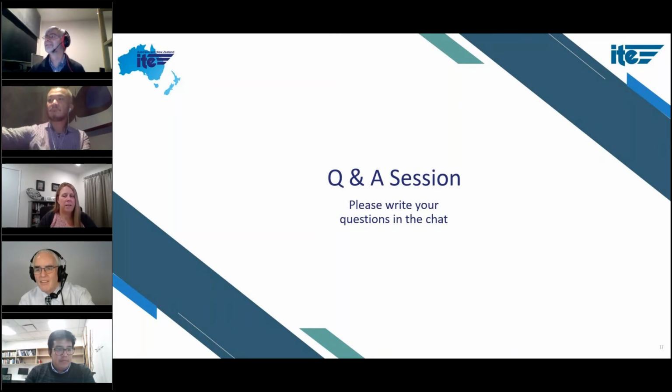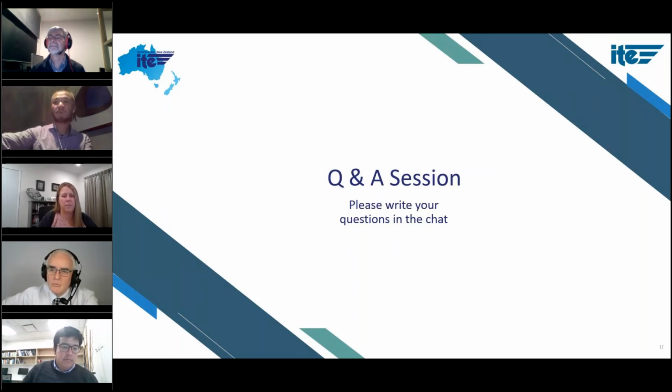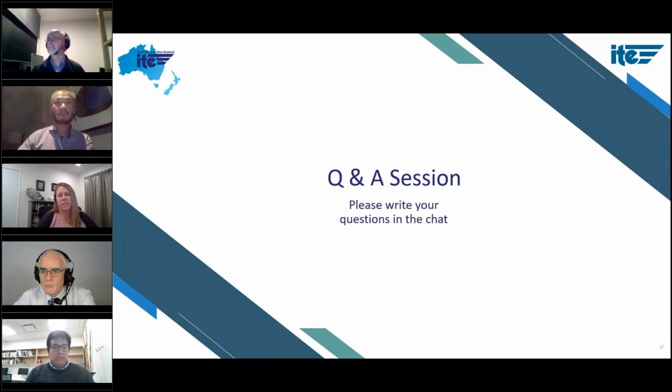I think just on that, my last comment comes back to understanding the purpose of the modelling, and also what you're going to do with the model beyond just the base calibration. I've had scenarios where, as Mark alluded to, you can produce the best calibrated model, but because you've had to change so many parameters, the flexibility for that model to reflect road network changes or things like that is actually limited because you've almost locked in too many. So it's always important to keep an understanding of what you're going to do with it and validate what the key parameters are that will demonstrate net difference for the client.